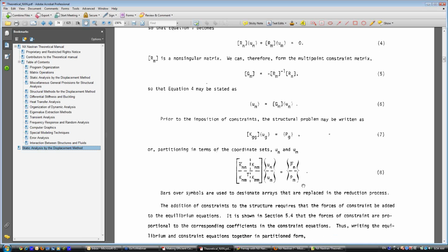I know this seems maybe way unnecessary, but where this is going to is that the reason why it's such a powerful technology is that if you couldn't use these sort of multi-point constraints to create your spiders and relationships for both heads, if you had to go back and use beam elements, extremely rigid small beam elements, you're creating terms in the stiffness matrix, and these terms would be very large, and it could cause the matrix to be, they would call it ill-conditioned.